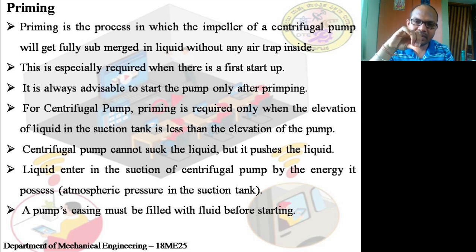When this water enters the system, it overflows. It displaces the air which has been entrapped there, and it fills that place with water. Then it will be closed. This process has to be done before starting the pumps. Once you start it, it cannot be done, and while operating also it cannot be done. Please be careful. Now you replace the water and we close it.